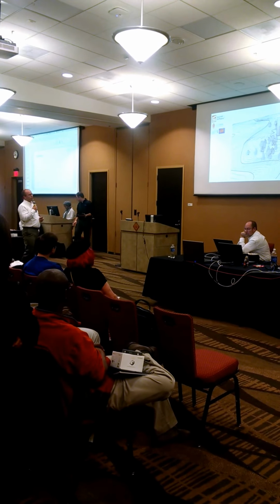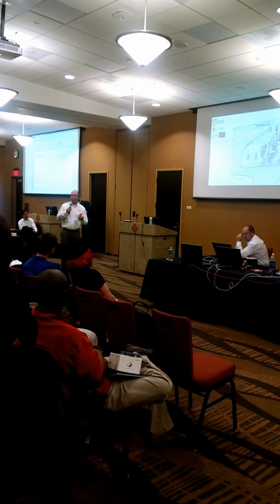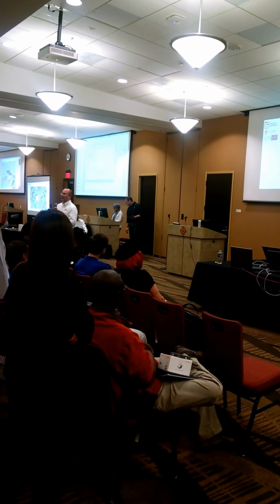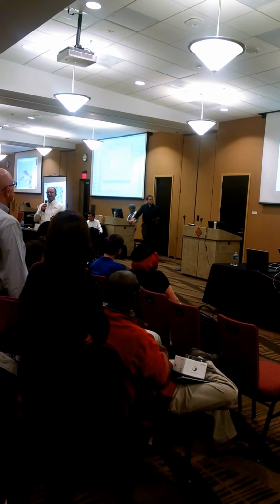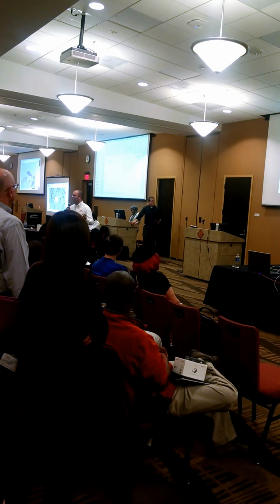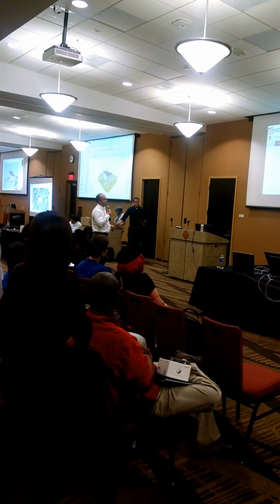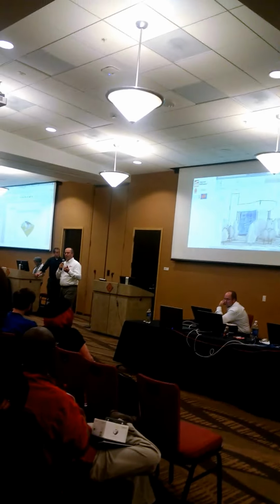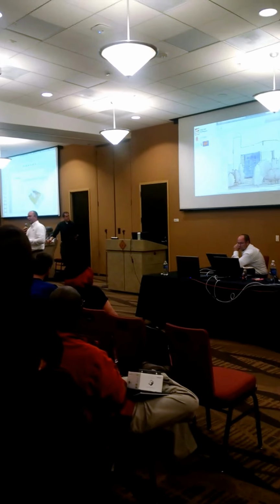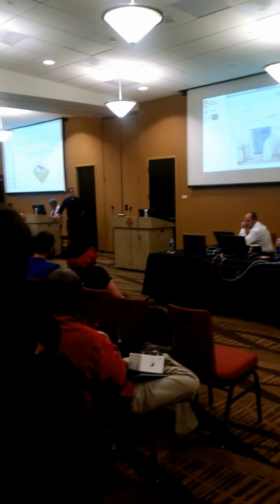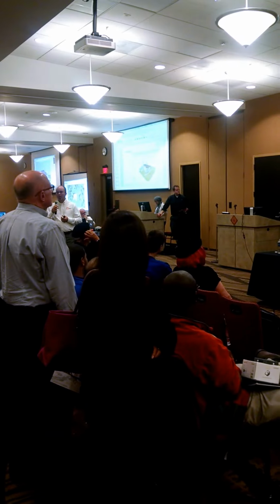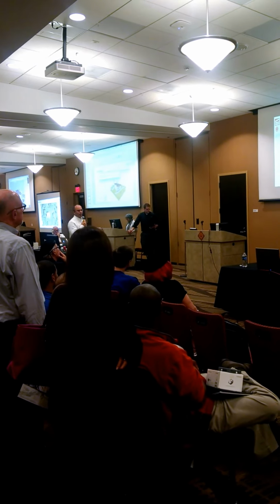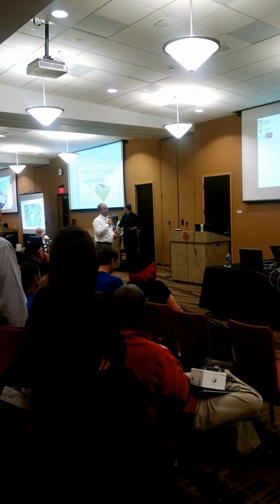It's not one of these final type of renderings, but this is what I call a byproduct of using Revit. I have the model information, I have my plans, I have my elevations, I have my sections. Let me just show some different views, some different perspectives of this to see how this building basically looks in it. Any of the views that we're working in with Revit are live interactive views. So you can see the wall is selected there, even though we're in an elevation type view. And the idea is that we can touch and pick and work on different things, no matter what area we're looking at. It's really whatever makes sense to where we're at.